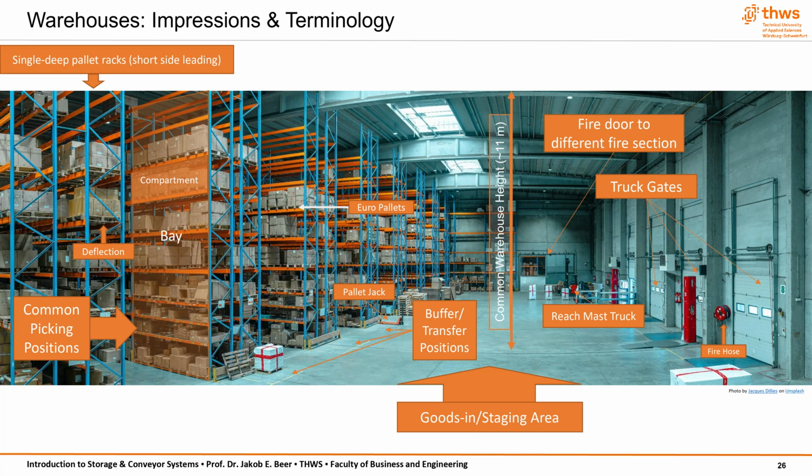From a functional perspective, fire doors must strike a balance between safety and usability. In day-to-day operations, they are often left open to allow for the smooth movement of people, pallets, and equipment. However, they are typically equipped with sensors or fusible links that automatically close the door in the event of a fire alarm or elevated temperatures. In some cases, they are connected to the building's fire alarm and suppression systems to ensure synchronized responses.